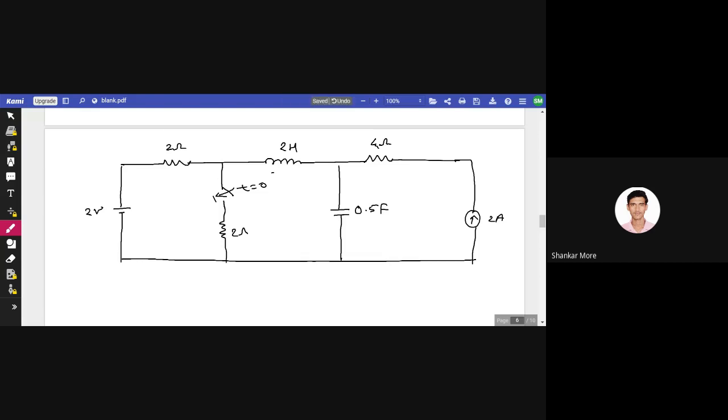Okay, so what I was talking about, yeah, I was talking about the inductor. So inductor connected है voltage source के साथ में, इसका मतलब वो short circuit है, and when it is short circuit, that means some current is supplied to the capacitor also, and capacitor को अगर current supply हो रहा है for an infinite duration of time, then in that case the capacitor will get fully charged and it will act as an open circuit, its terminals will be open.